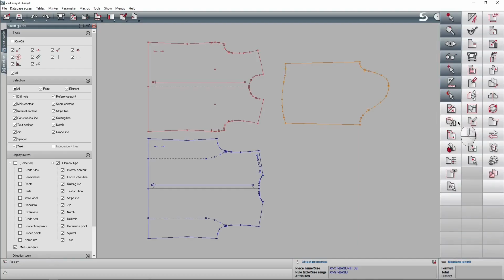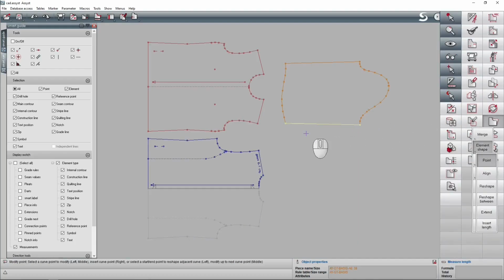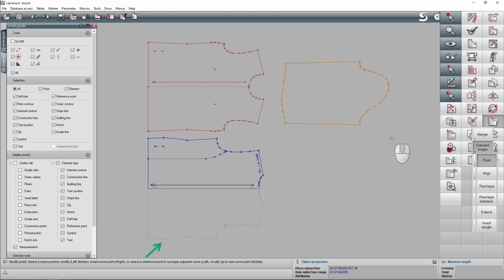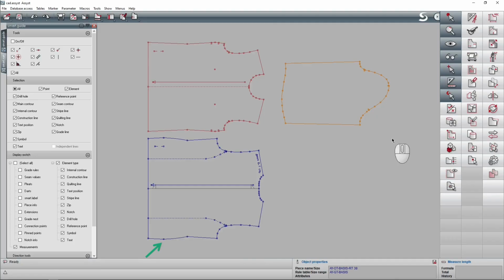The particularity of the mirror pieces is that they have one active half. All modifications are done on this active side and they will be directly mirrored on the other side. What is the difference to this piece for which both sides have been constructed independently? This piece looks symmetrical but both sides are active and there is no dependency between the two sides.